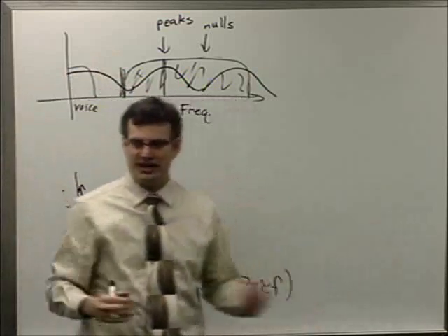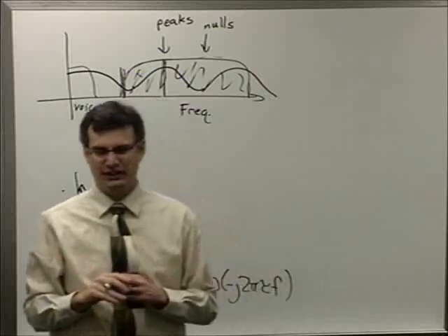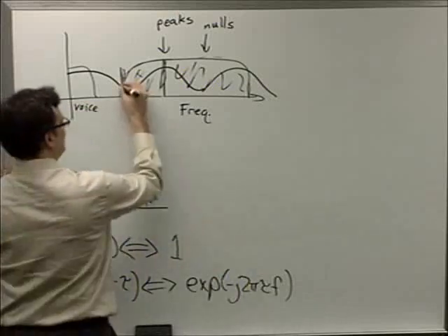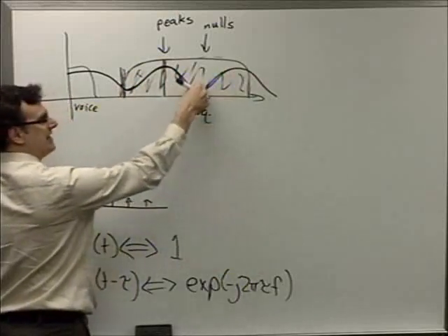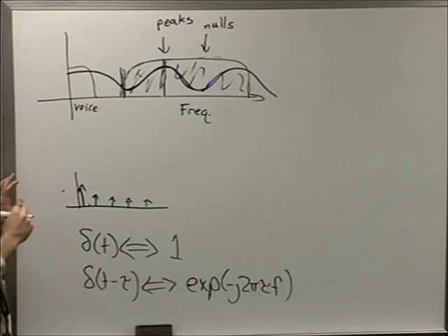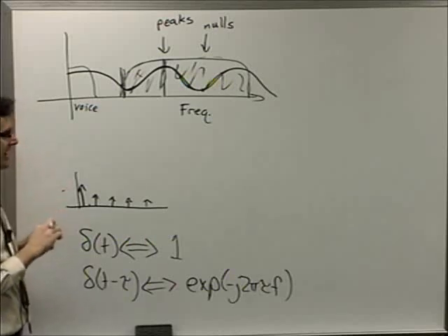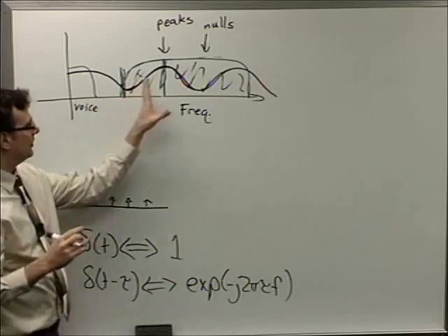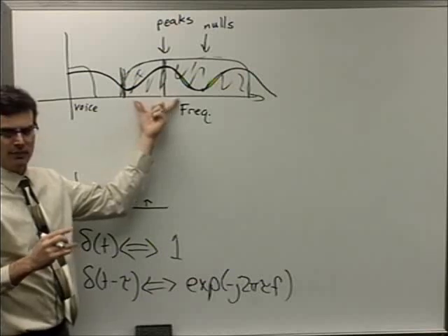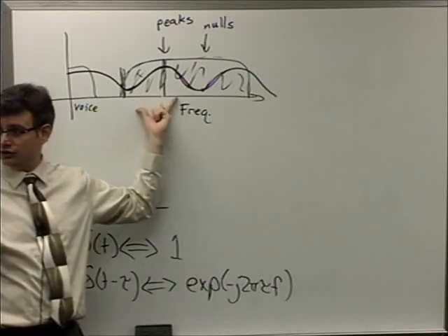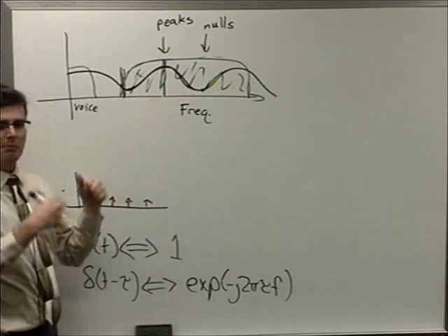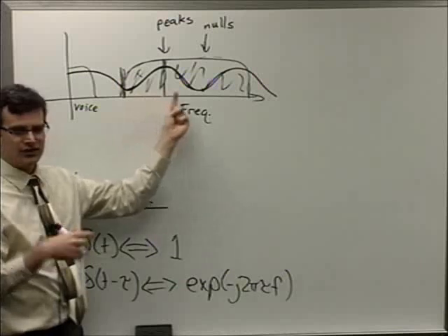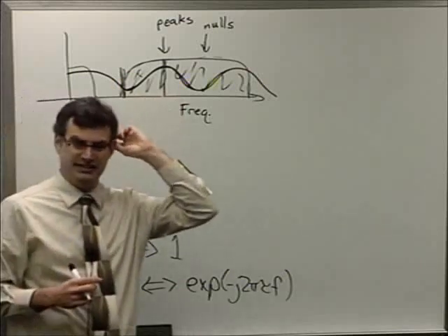And that's why you used that kind of transmission line, which wasn't particularly good or well matched for anything when you first deployed your telephone system. But you want to take advantage of the fact that you've got this extra bandwidth, but there are some bad spots. And the way that they do this is actually quite interesting. You take, instead of transmitting a single high-speed signal up here that would be distorted, kind of like the one that I showed you in the graphs, you do a bunch of really slow signals, and you modulate them on different carriers.